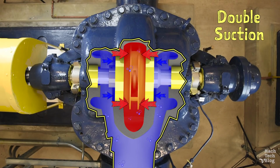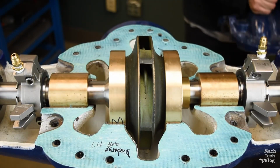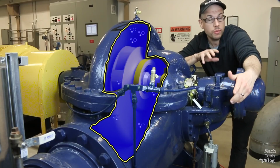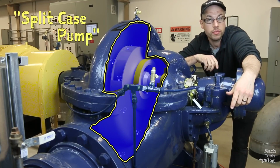due to pressure imbalance. And this design has another key advantage. The suction and discharge piping are normally positioned parallel to one another on opposite sides of the pump, and the casing is split axially so that just by removing some bolts and pulling the cover off, maintenance technicians can access the rotating assembly inside the pump without removing the whole pump from the system. This axially split design is why pumps with impellers between bearings are more commonly referred to as split case pumps.